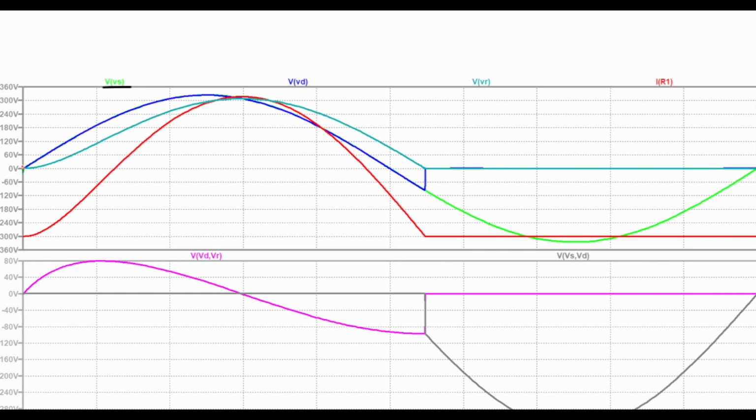So we are starting here at t equals to 0, and the input voltage is positive. The resistor voltage Vr is less than Vs, so Vs minus Vr is positive in this region, and thus the current, as I explained, IR, should be increasing.